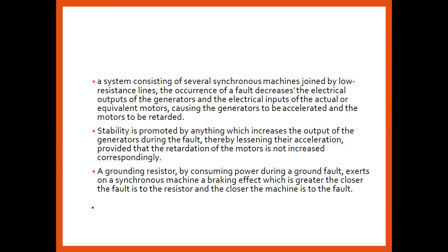Okay, so the grounding resistors, by consuming the power through the ground fault, exert a braking effect on the synchronous machines, which is generally greater the closer the fault is to the resistor and the closer the machine is to the fault. So the grounding resistors and reactors are generally useful to amplify the grounding effect, to lower the severity of the fault on the different apparatus of the power system, and to improve the stability of that power system.